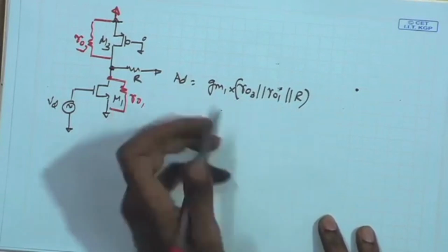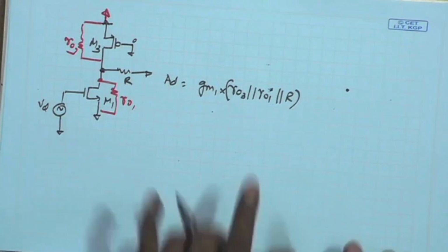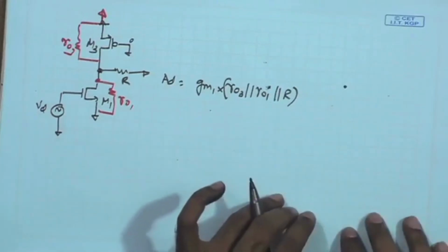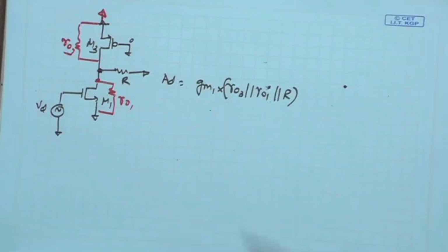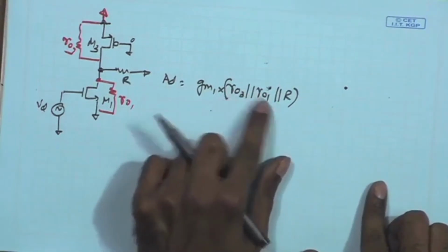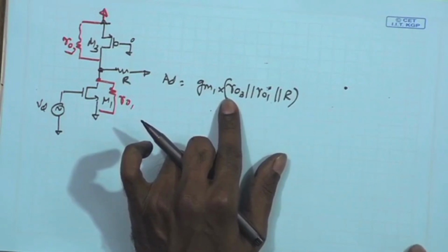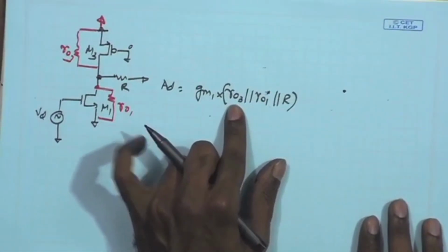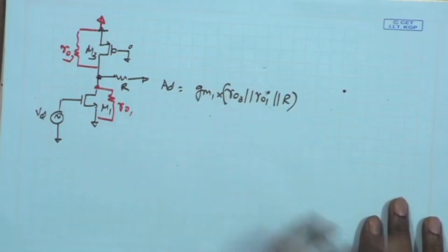Now this requirement will definitely make us think that there are going to be a lot of constraints, because we are looking for lower current, so that we can reduce our power dissipation. We also want larger open loop gain, that would also enforce lower bias current, and that would mean very large RO1 and RO3. So, in 180 nanometer technology, if you are going for bias currents of the order of 10 microampere, RO values can easily approach hundreds of kilo ohm to 1 mega ohm, especially when you use longer channel lengths.